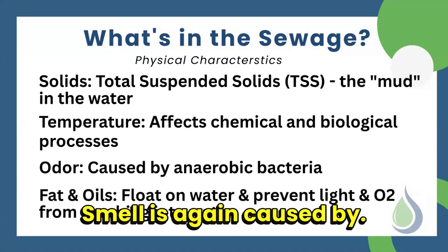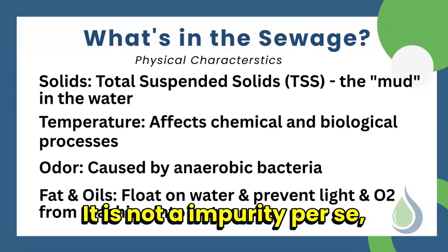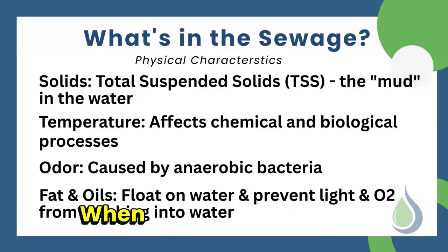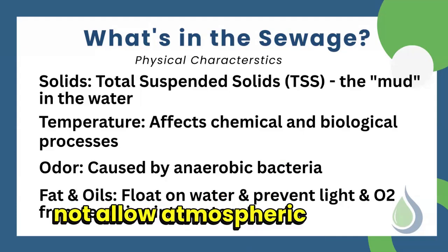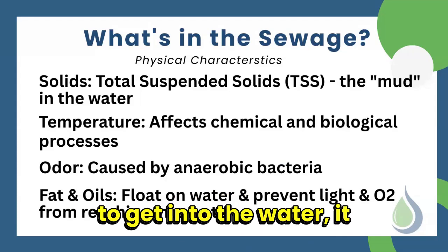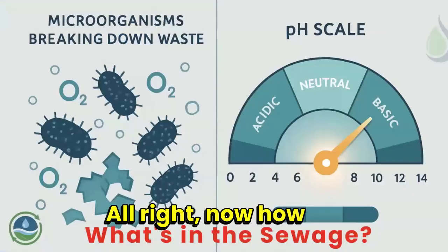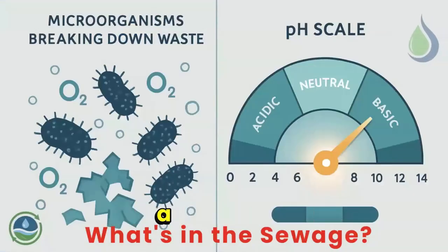Smell is again caused by, it is not an impurity per se, but it is caused by bacteria. It is caused by oil and grease. When oil and grease does not allow atmospheric oxygen to get into the water, it generates a foul smell. All right. Now, how are we going to remove it? Let us go to that a little later.